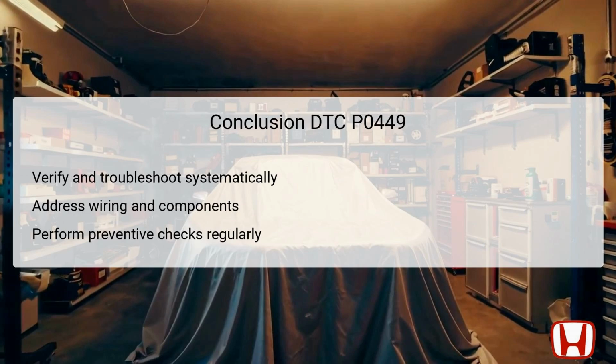In summary, effectively diagnosing and addressing DTC P0449 requires a systematic approach. Verification of the issue starts with the HDS, prompting further investigations into wiring and component integrity. Open circuits in the harness can often lead to miscommunication and improper functioning, highlighting the importance of comprehensive electrical testing. The importance of maintaining the EVAP system cannot be overstated, as it directly influences vehicle emissions and performance.